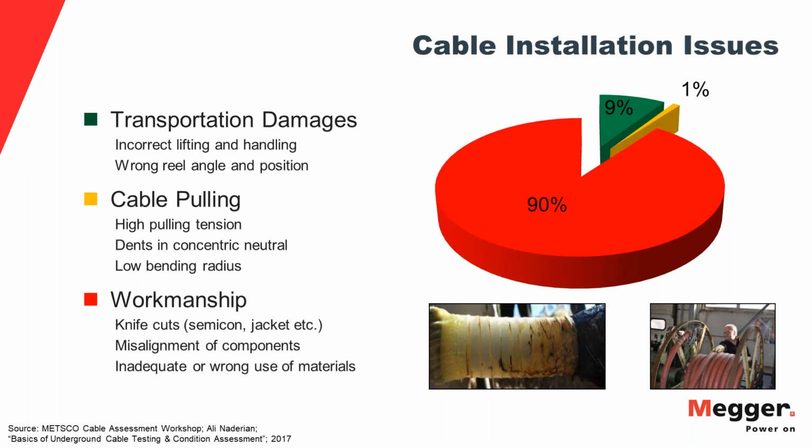Also, when you work in the trenches and a day of work is finished, make sure the exposed ends of the cable are covered, so there's no chance that moisture can get into the cable, which in the long term will cause accelerated aging. And then you will see this sooner or later during the tan delta testing.